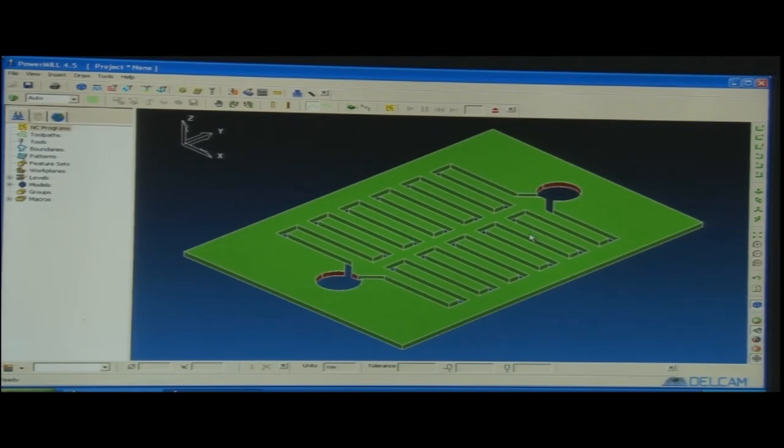to work. So, whenever we generate the code, whenever we start the machining conventionally by hand or using a CNC machine, we have to take care of these 3 major things, again machine tool, cutting tool and the job that is to be cut. So, the coordinates have to be set accordingly, so that the reference point for the machine tool, cutting tool and the job is the same. So, this is one of the major concerns when we talk about CNC machining, the reference point. What is the starting point that is put in the software? What is the starting point where the tool touches the workpiece actually on the machine?